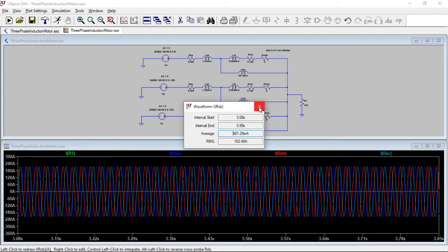That's a property of a balanced three-phase system: you don't really need a neutral wire for this Y-type connection here. But if it's unbalanced or something happens, then you're going to get weird stuff.